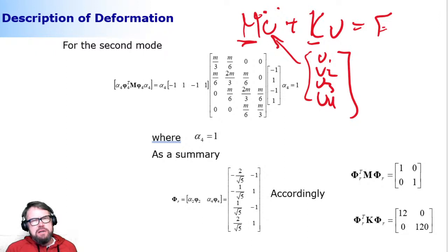Of course, we can compute deformation using all the modes. That's going to be the accurate solution, and then start reducing the modes and monitoring when the solution is no longer acceptable. But that's only in theory, because these eigenvalue analyses are not suitable to compute 100,000 different modes. They don't really work well for that purpose.